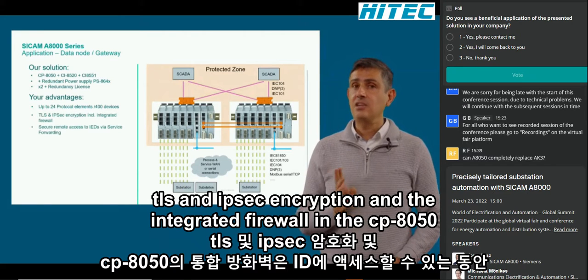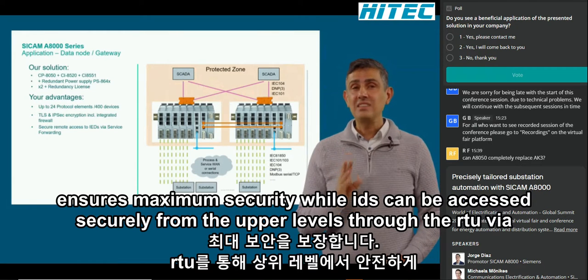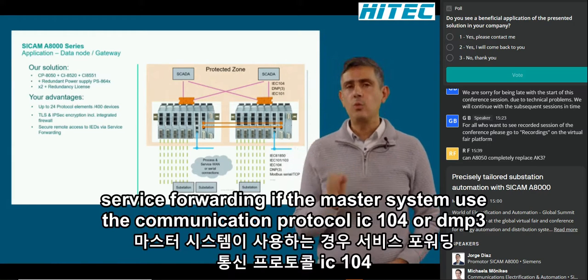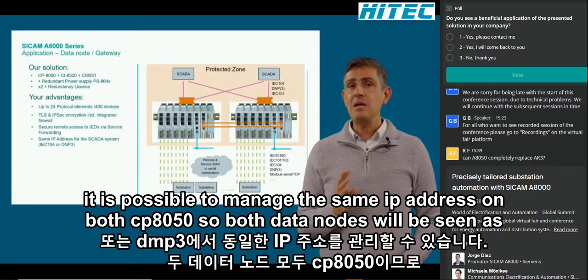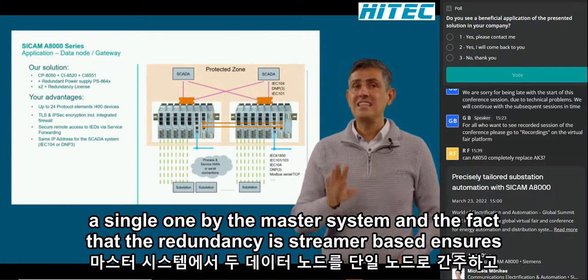TLS and IPsec encryption and the integrated firewall in the CP8050 ensure maximum security, while IEDs can be accessed securely from the upper levels through the RTU via service forwarding. If the master system uses the communication protocol IEC 104 or DNP3, it is possible to manage the same IP address on both CP8050, so both data nodes will be seen as a single one by the master system.